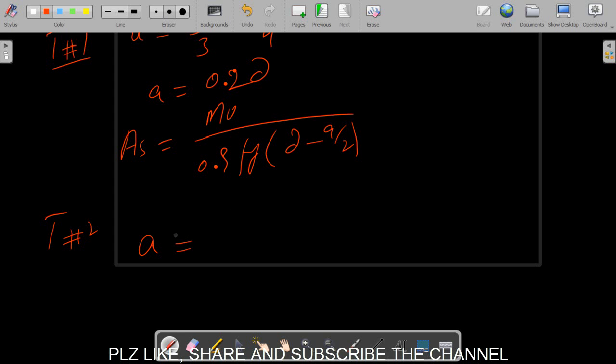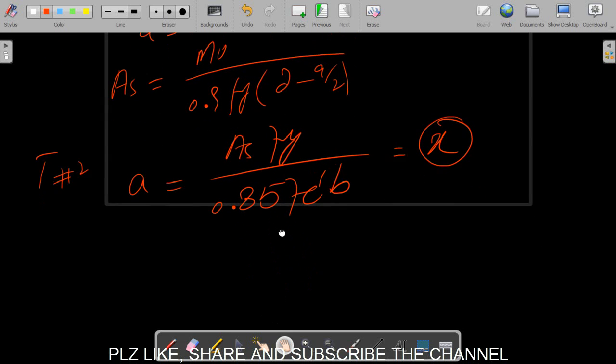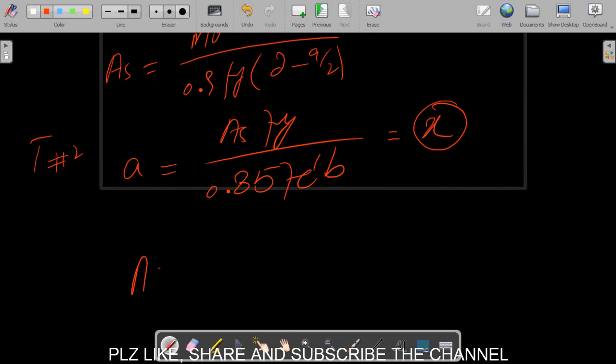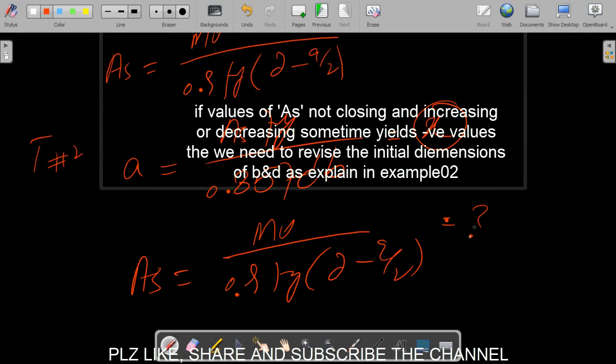We will calculate the value of a, that is, area of steel times Fy divided by 0.85 Fc prime into b, and we will check this a value, which we calculated right here, with the assumed value. If it is close, we will stop the trials and we will calculate the final value of area of steel from that equation, Mu divided by 0.9 Fy into (d minus a over 2), and that one will be our desired value.